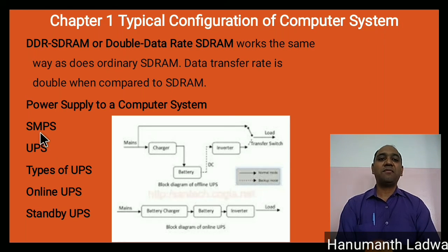Generally a 15-inch color monitor requires a 500 volt ampere UPS, and a 17-inch color monitor requires a 600 volt ampere UPS.